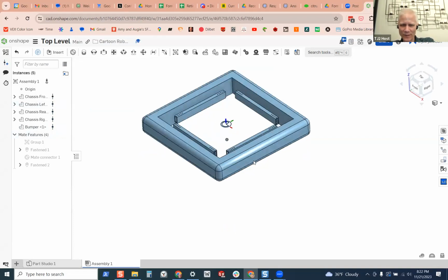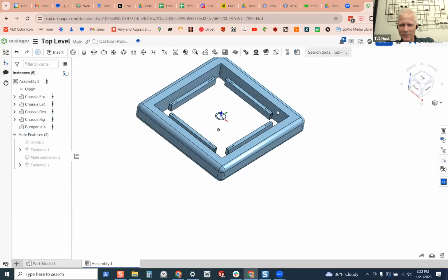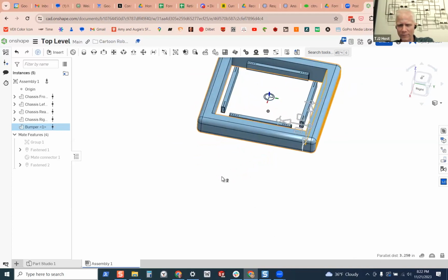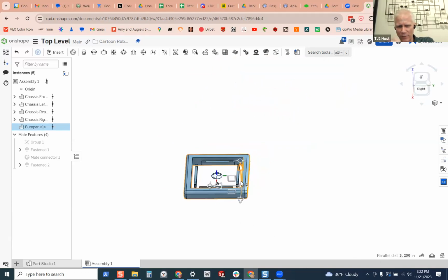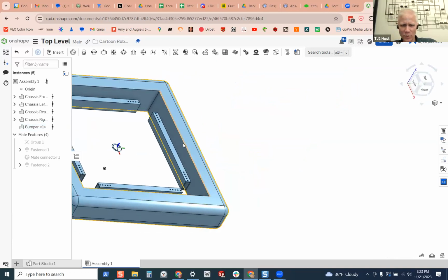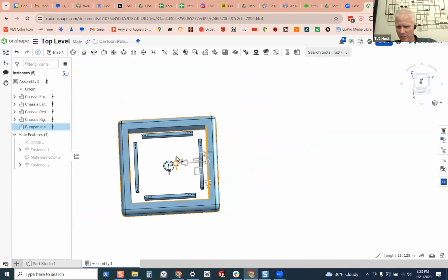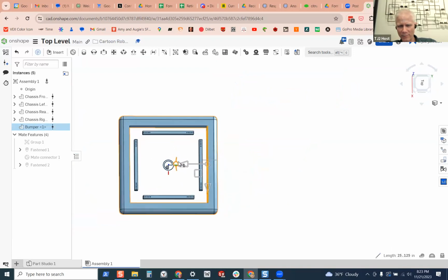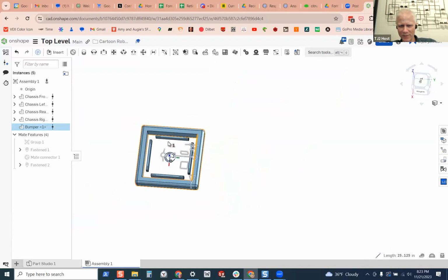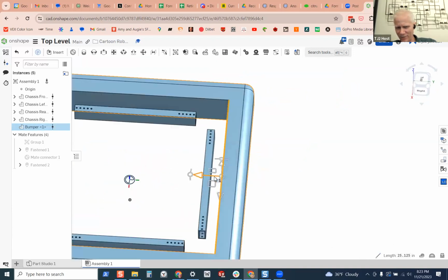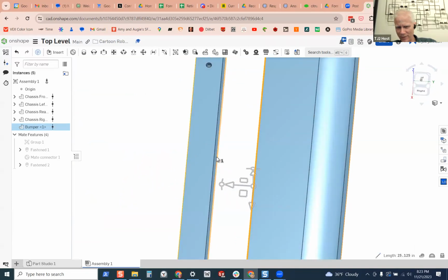Okay, cool. Yeah, let's see. So if I measure from that point to that point, it's now 1.25. Yeah, that is the right number. So that's cool. And what about if I measure how long this wall is? Yeah, 25 and 1/8. Nope, that isn't right. It should be 25.25, because what I want is a bumper. Actually, I'm looking at you, Owen, and saying something isn't right here, because it's 25 and 1/8, and this looks like a way bigger gap than a 16th.